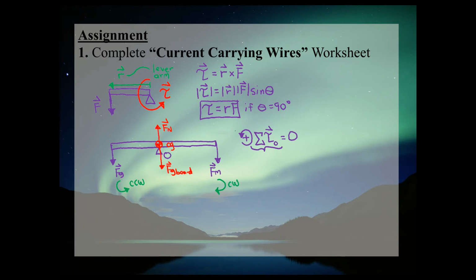We'll expand the torque equation. What this means is if the force generates counterclockwise torque, we're going to write down a positive sign in front of it. If it generates clockwise torque, we're going to put a negative sign in front of it. So this would become positive, the torque generated by the force Fg, that's from the hanging mass, subtract the torque generated by the magnetic deflecting force, and that's equal to 0. We want these two torques to cancel off, because if they cancel off, there will be no net twisting force, and then the teeter-totter is not going to rotate.